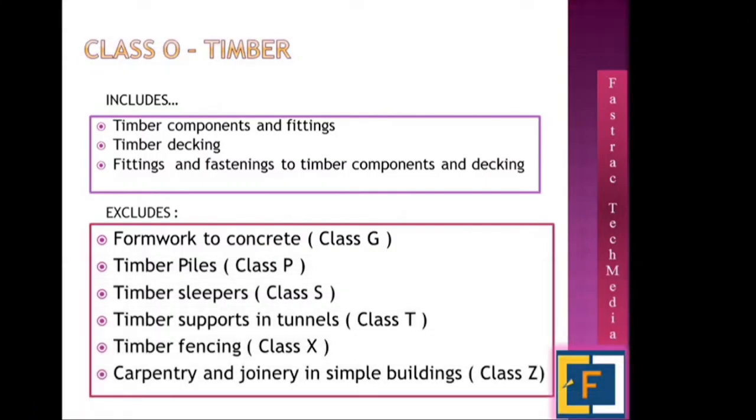See, timber supports in tunnels, that is separate in class G. Timber sleepers, class S. Timber piles, class P. Formwork to concrete, class G. Again, what is timber including in class O? That is timber decking. So you have to understand where this timber decking is coming. Components and fittings in timber. So where are these things coming?